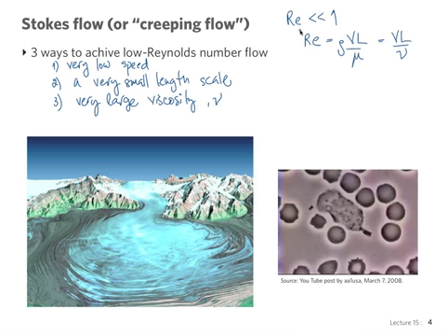In fact, because the Reynolds number is much smaller than 1, you can actually say that all of the inertial effects are negligible and completely eliminate that. So basically, imagine that the Reynolds number is much smaller than 1 because the velocity is very small. In the Navier-Stokes equation, we have this nonlinear term that multiplies velocity with the gradient of velocity, right? The derivative of the velocities.